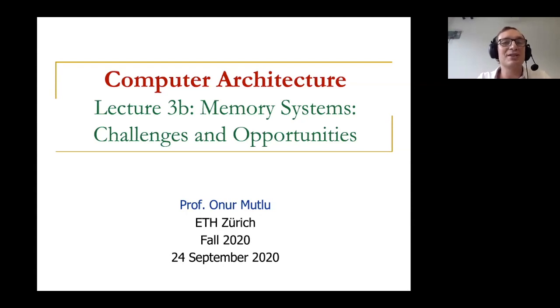And it turns out one of the interesting ways of recovering happens by inducing more errors into the flash chip. So let me give you the basic idea very quickly because I find it fascinating. Okay, you got an error. Let's induce more errors and examine the properties of different cells. Before that you checkpoint the flash drive so that you don't lose the data that you have. Okay, let's induce more errors. Now, once you induce more errors, you understand the different properties of different cells. And based on that, you can guess which cells were more vulnerable when you got the error.